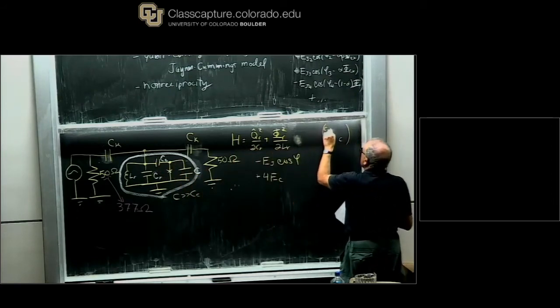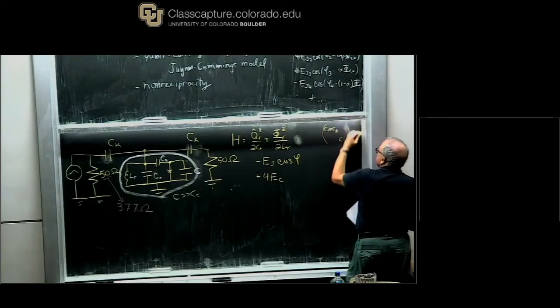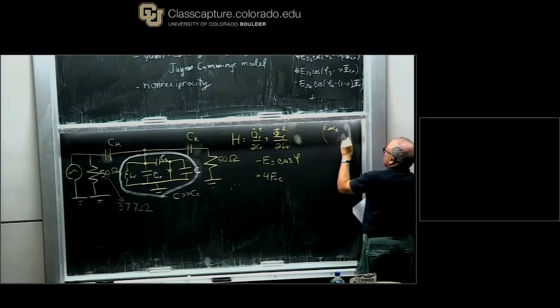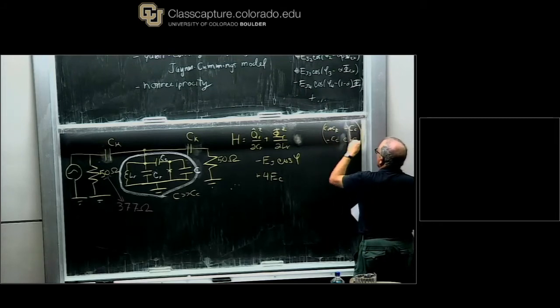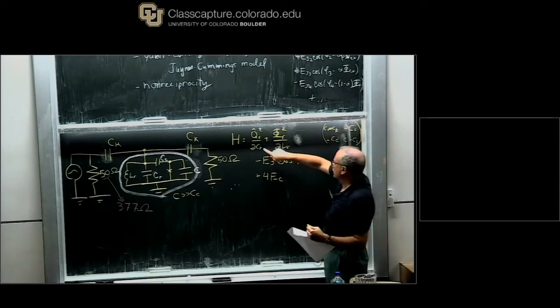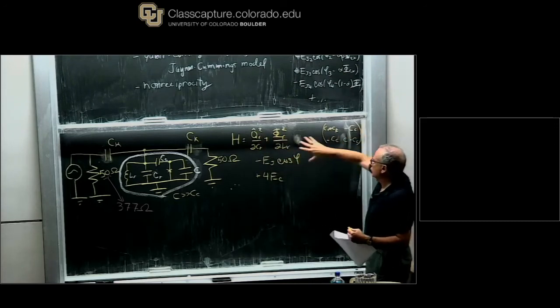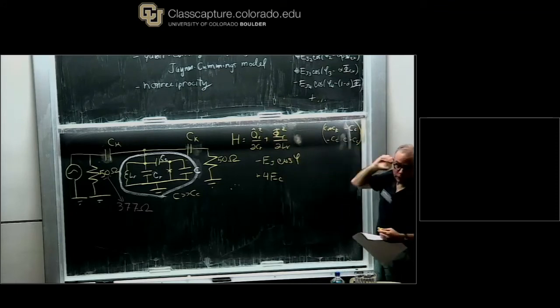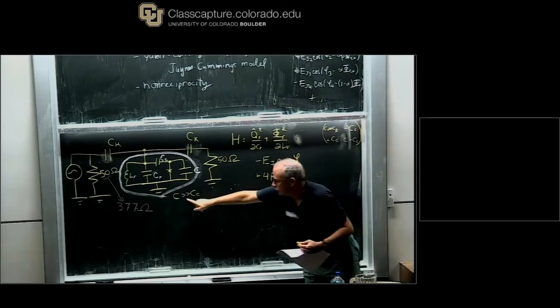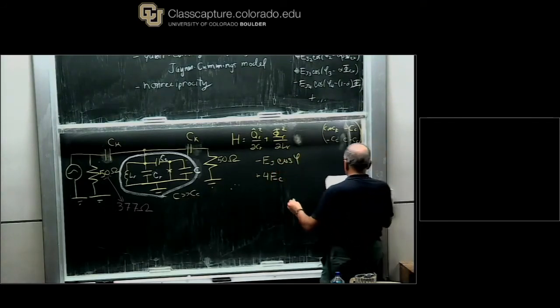And that means I get to enter it four times, C sub c on the diagonal, and then minus C sub c here, and that's the exact capacitance matrix. We have to invert this in order to really give the parameters in the Hamiltonian. But by writing what I've written here, I'm doing an approximate inverse of this, which is only valid in this limit. So I'm doing an approximate, or you might say a perturbative, inverse.